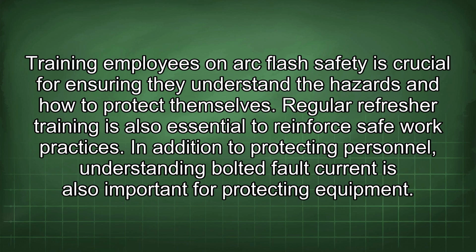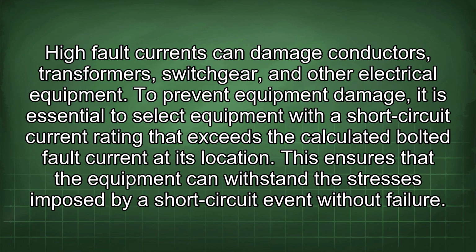In addition to protecting personnel, understanding bolted fault current is also important for protecting equipment. High fault currents can damage conductors, transformers, switchgear, and other electrical equipment. To prevent equipment damage, it is essential to select equipment with a short circuit current rating that exceeds the calculated bolted fault current at its location. This ensures that the equipment can withstand the stresses imposed by a short circuit event without failure.